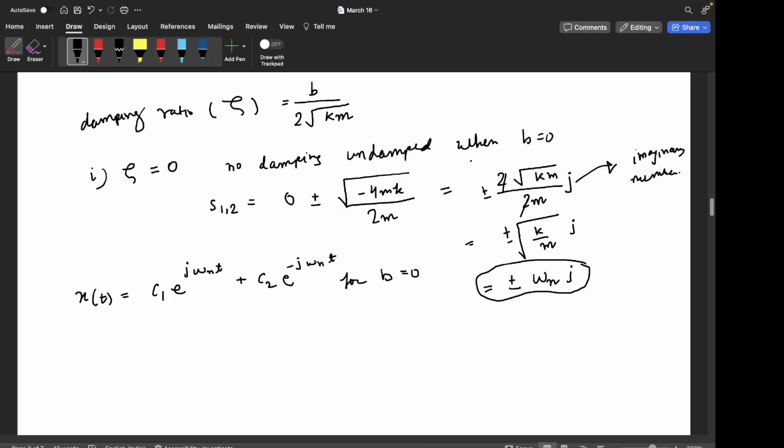And the over damped case, I will just be discussing next, is when this xi term is greater than 1. So when you will be designing that damper, you will choose the damping of that damper in such a way that this xi comes out to be greater than 1, and in that case, the over damped case, the second order system shows no oscillations. So I will also sketch out typical responses. So the system dies down or goes to its steady state value without any oscillations.